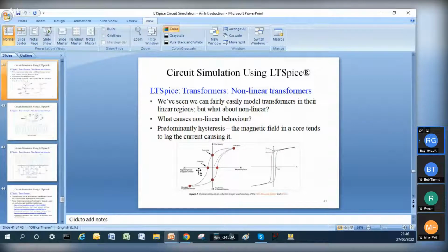If you extend that by increasing the voltage across the primary or increasing the magnetizing current, there comes a point where the core will saturate. And at that point, it's no longer linear. You're no longer getting an increasing current for an increasing voltage across the winding. At that point, things go rather south.